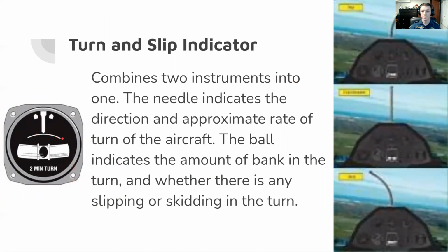Basically, how this works is it's another indicator that's going to take the direction and the rate of turn of your aircraft and figure out if you are in a stable turn or if you're slipping or if you're skidding. Slipping and skidding are when you're applying too much or too little rudder and you're not synchronized with the airflow as you turn your aircraft. Sorry, just a small correction. They are in Cessnas, they're not in gliders. We have a yaw string in the glider, and that operates a little bit differently.